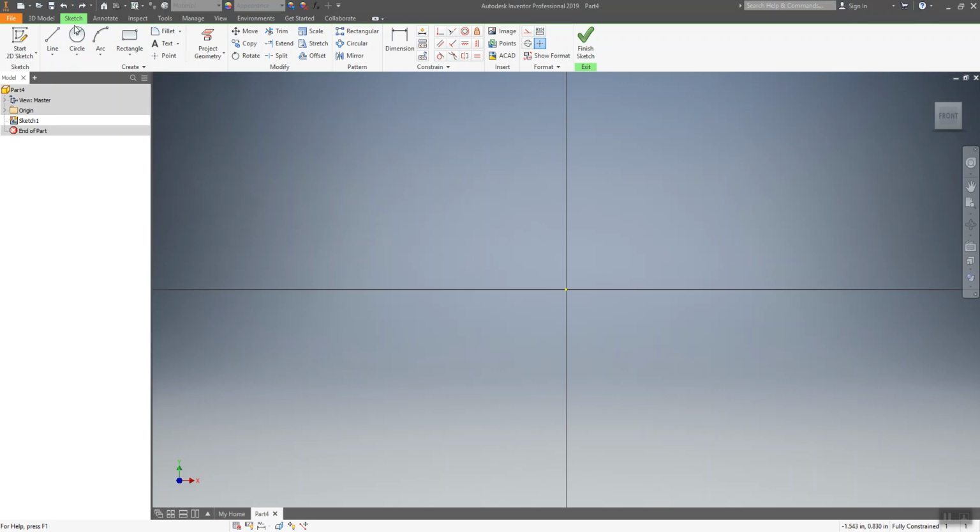And I'm going to undo those lines. Now let's create a line using the heads up display. So as I move my cursor to the center origin, it turns green. That's going to create a coincident constraint. And now I'm going to make my horizontal line, but you now see, or maybe you notice, that there is a highlighted text. In this case it's 0.754 inches. If I know that my line needs to be 1 inch, I can actually just type that in as 1, or you can put 1 inch.